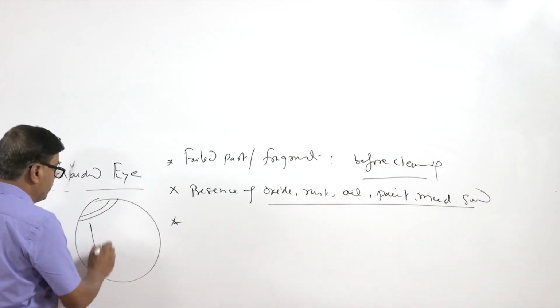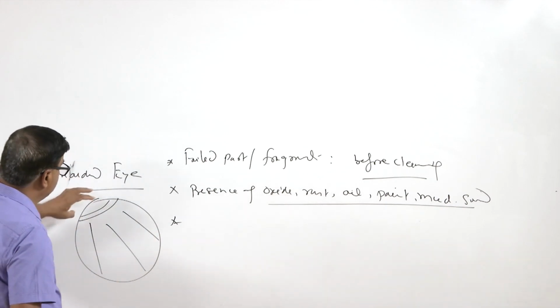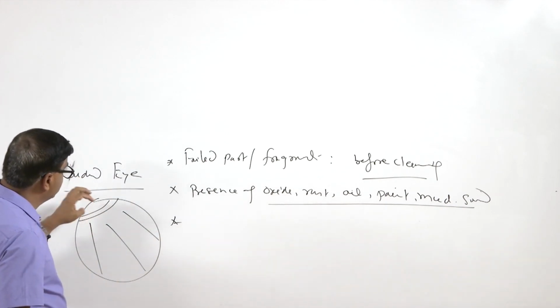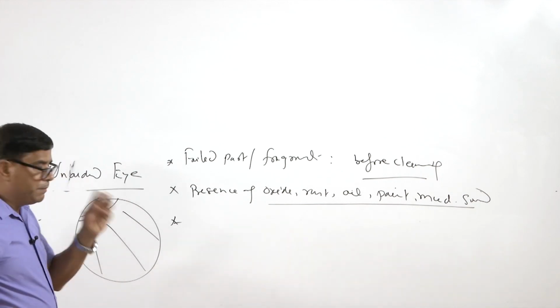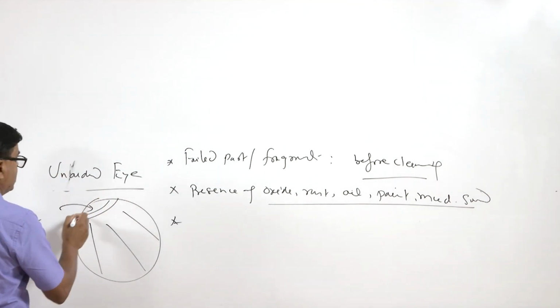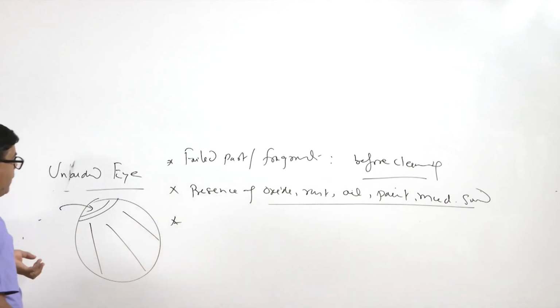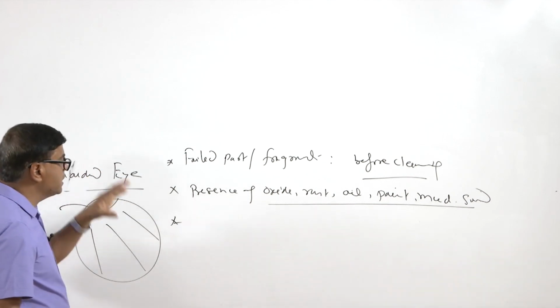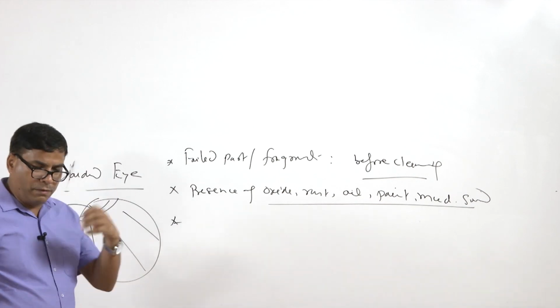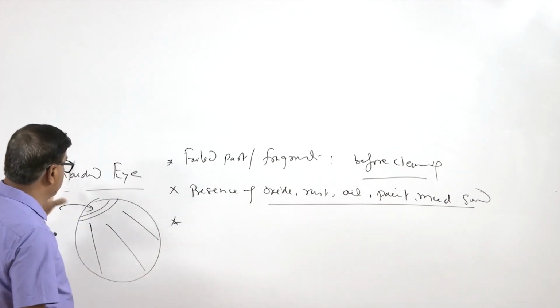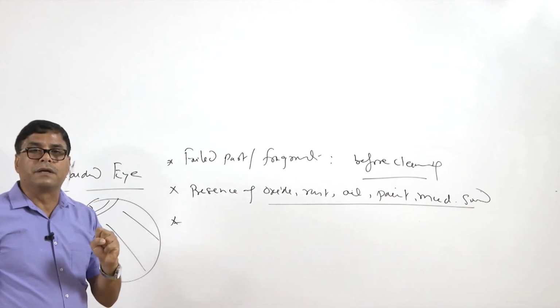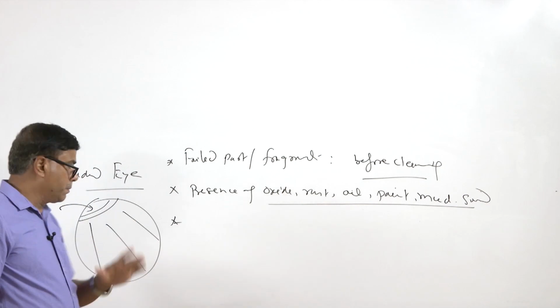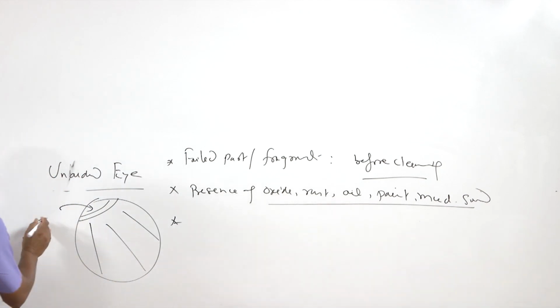The remaining zone might have failed one way, but this location is different, which might be due to the presence of discontinuities, stress raisers or stress concentration, poor mechanical properties or something else. So, it will lead to the identification of an area which is unique and present on the fracture surface. So, this area becomes the area of interest,